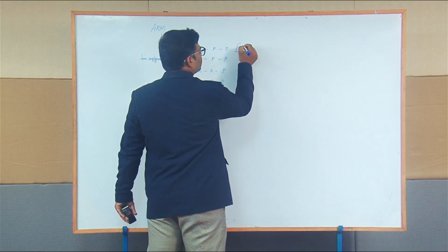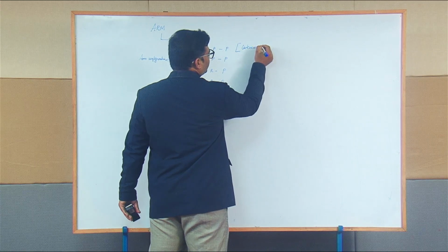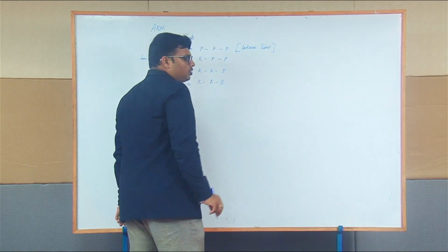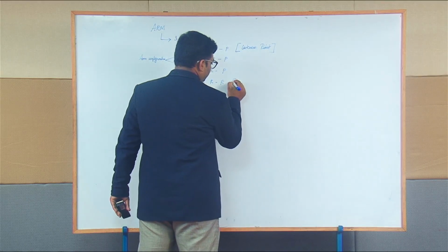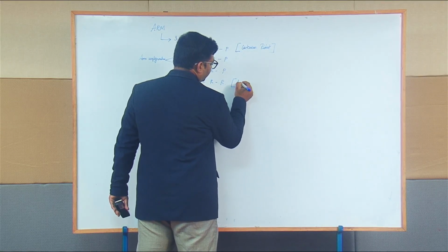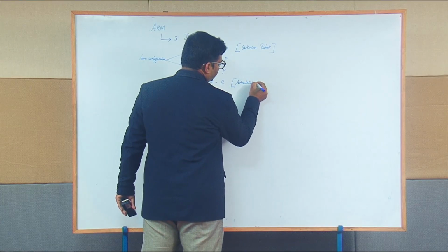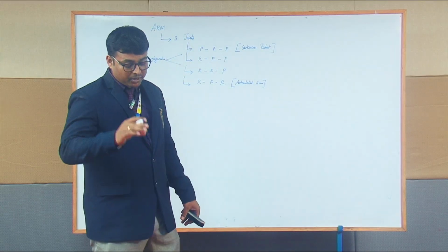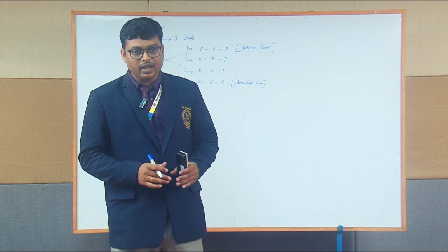We name it as Cartesian robot if it contains 3 joints to be as linear, and at the last we call it as articulated arm configuration since all the joints are rotary, which is nothing but your human arm. Your human arm contains all 3 joints to be as rotary.